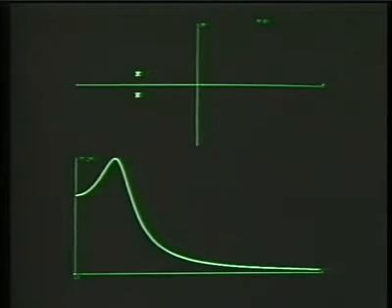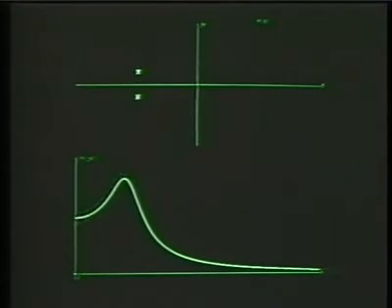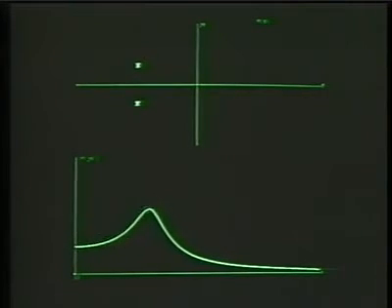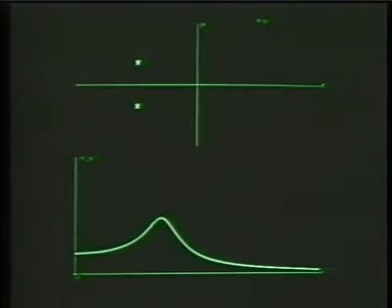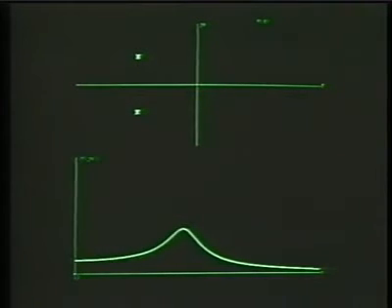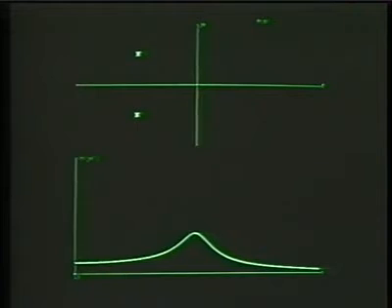And finally, what we'll now do is move the poles back to their original position, and the resonant peak will, of course, shift back up. And correspondingly, the height or amplitude of the resonance will decrease. And now we're back at the frequency response that we had generated previously.